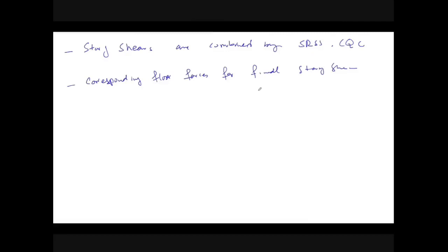There is one other thing that we have to note: the force calculated from the design response spectrum shall be divided by a quantity R over IE, in order to produce the design level forces.